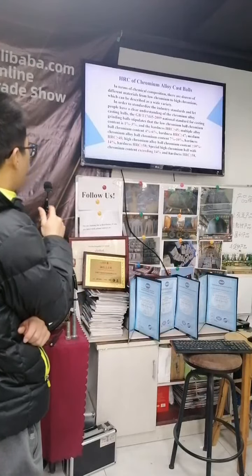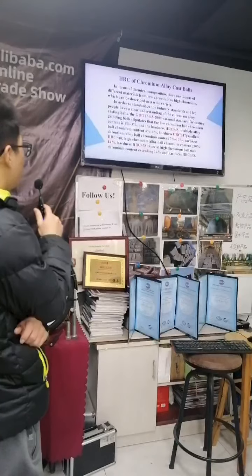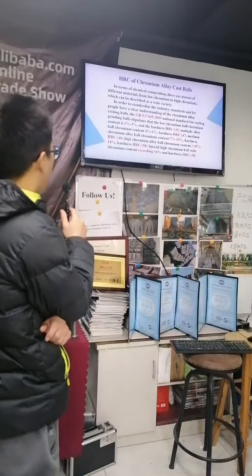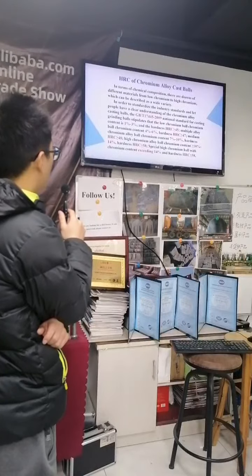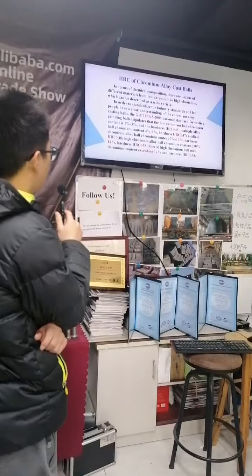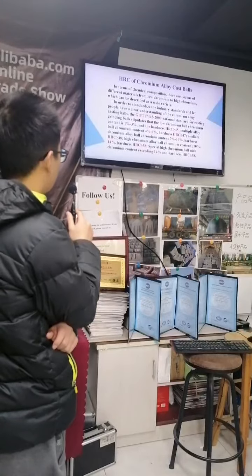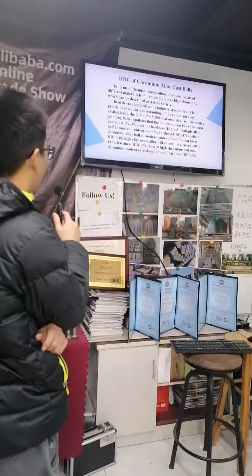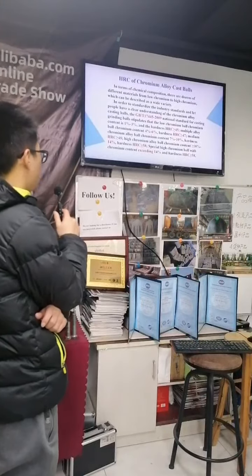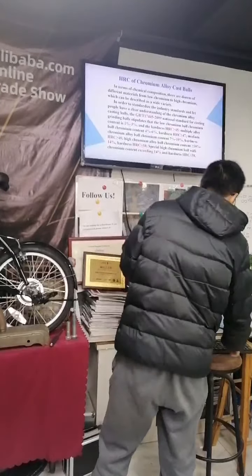Medium chromium alloy chromium content is 7% to 10%. Hardness HRC more than 48. High chromium alloy chromium content is more than 10% to 14%. Hardness HRC more than 58. Special high chromium alloy with chromium content exceeding 14%. Hardness HRC more than 58.